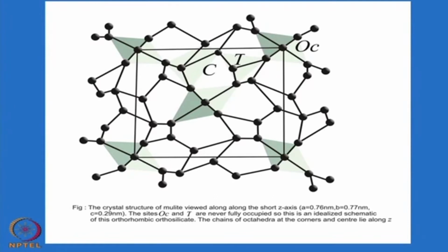This is not a pure silica, of course, it is another structure. It is mullite. The chemical formula of mullite is 3Al2O3·2SiO2. This is a silicate, and it has its own structure. It is not related to the Al2O3 structure or the SiO2 structure, but is a completely different structure with a distribution of silicon and oxygen as well as silicon and aluminum, and this is the structure.